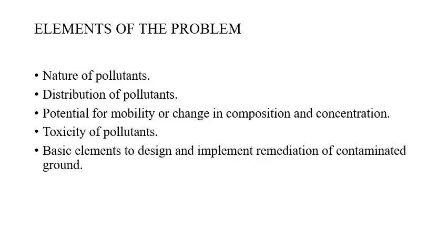Okay, so basically, if a contaminated land is presented before a geoenvironmental engineer, then he has to do a thorough site investigation to understand what are the surrounding areas and what are the possible receptors of these contaminants. For that purpose he has to do a thorough site investigation and site inspection, and finally you need to understand what are the types of contaminants that have gone into your subsoil.